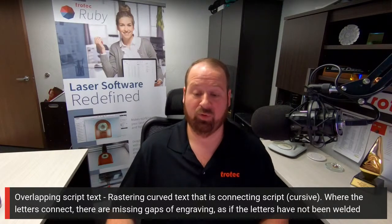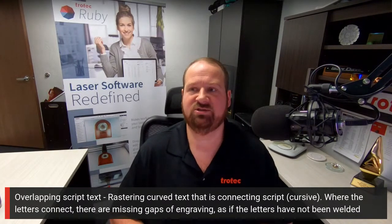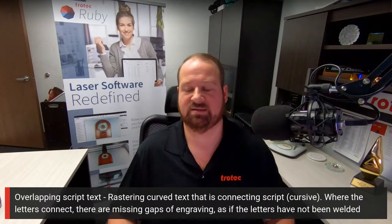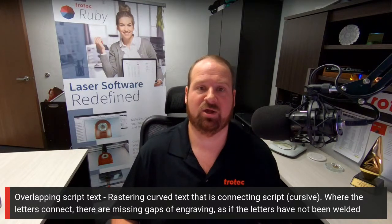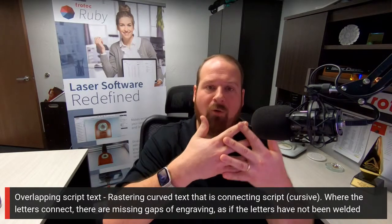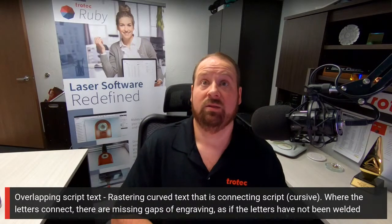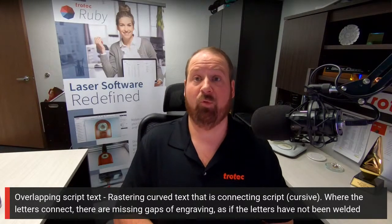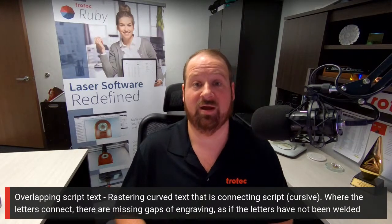Okay, so for example, in this case where you have script text, that is interesting. I think this is an import error, because if you convert it to an outline, so you just see the outline of that text, you'll notice that with cursive fonts, when the lines are together, you will literally see an overlap. So this has to be an error that Ruby is doing. The only way I can think to resolve this right now, and that is definitely a bug from what I can sense, is to convert it to curves. So convert that text to curves so that it comes in properly.